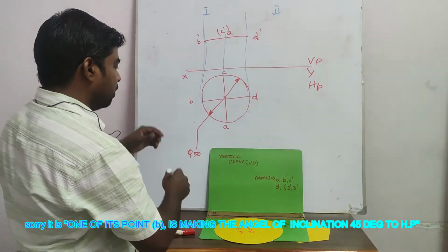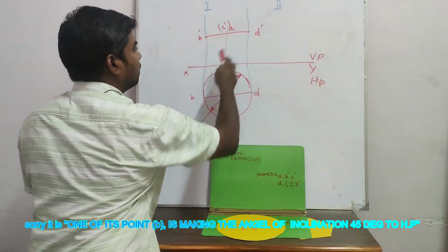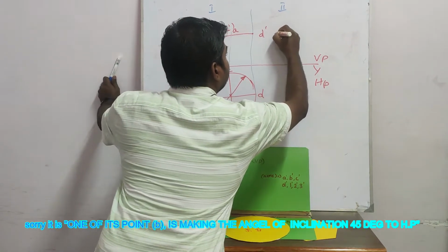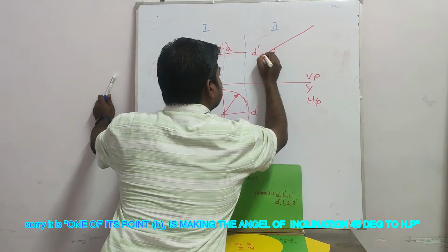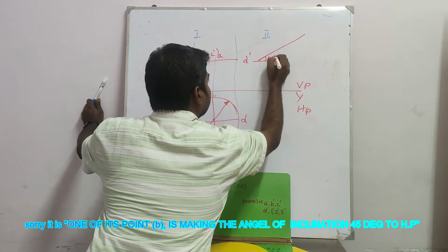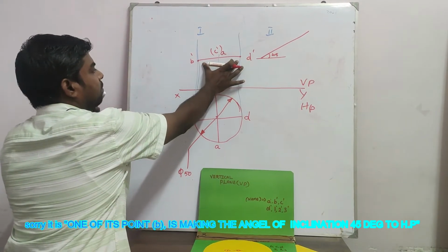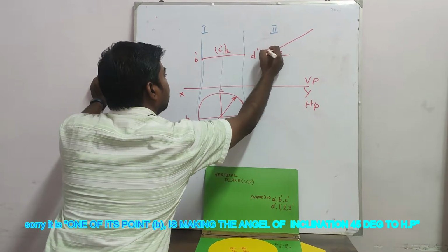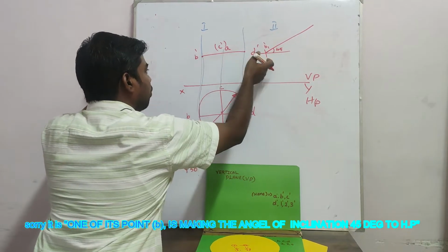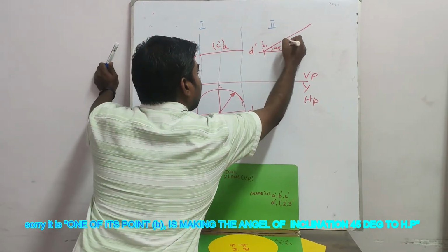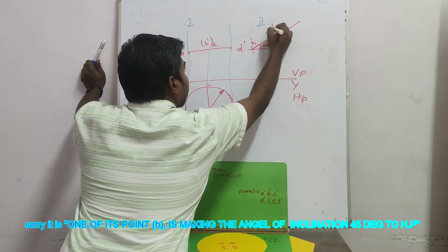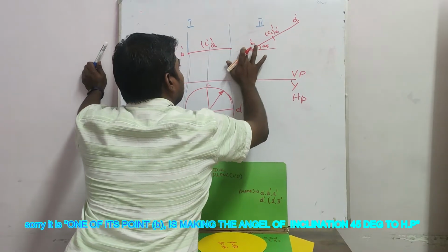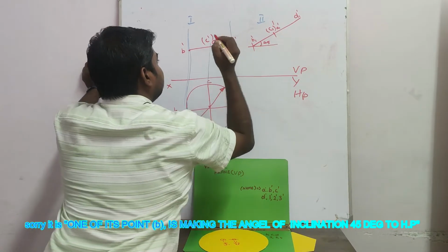That is very easy. So what we have to do is, for this distance you have to mark one point here and make a 45-degree inclined line. Okay, use extended lines here, make 45-degree, and you know what the distance of this is. So reproduce this distance and reproduce the same names. Here it will be B dash, so reproducing one more time, B1 dash I am putting, and here C1 dash, A1 dash, and this is D1 dash. This, let me write here, D dash.